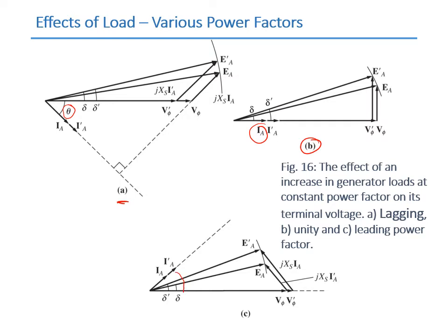And you can see for the first one, we already saw that the new Vphi will be smaller than the original Vphi, and for unity power factor, the Vphi is also smaller, but only slightly smaller. But when it comes to the leading power factor, you can see it's the other way around. The new phase voltage is actually larger than the original one.